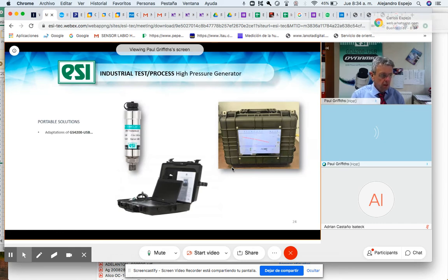Yeah. Okay. So in this case, I know I have a guy in Egypt who does the same sort of thing, and he has a box of adapters. So he has G quarter-inch BSP as a standard fitting, but he has a little box of adapters so that he can connect to any pipeline, any system. So you'll have NPT, BSP, metric threads, so we can just screw on an adapter and carry out a test anywhere. So people are quite inventive, actually.